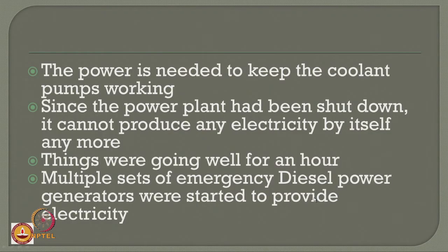So, there can be a study done here to understand the post accident scenario, so that this delay, or the phase delay created between the start of the diesel power source with respect to the power shutdown from the plant, can be minimized. So, one can do a safety process assessment here, which can be done either by doing a HAZOP analysis or using an FMEA again. So, now let us understand the scenario. There is no external power, electricity is disconnected, the nuclear reactor is stopped, heat is on, there is no radiation to be controlled, there is no power supply, and external power supply is now switched on using diesel power.